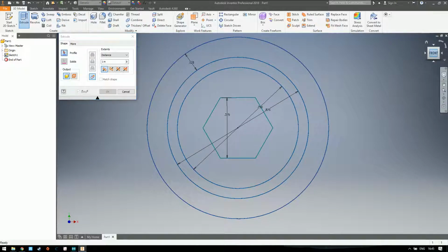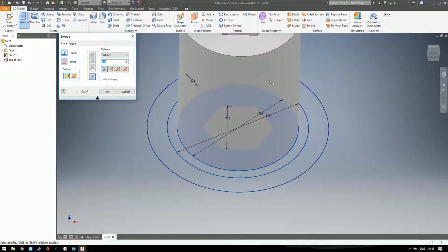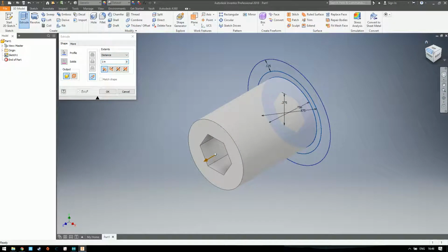You probably cannot see it very clearly, but it will light up the area you're supposed to extrude. If it doesn't allow you, it means you are not in a closed area. You click on the part where you want to extrude. It's supposed to give you a 3D demonstration of what you are doing right now.